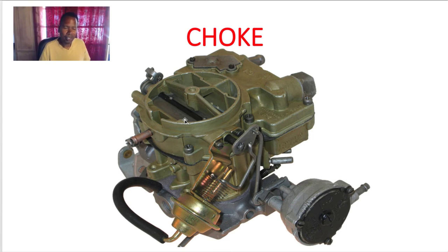I said this earlier, a cold start. Oh, I said this already. I forgot what I said. Oh yeah, when the car is cold, the air molecule is much denser. You need more fuel on a cold car. So what you need is a richer air fuel mixture. When this car is cold, this choke needs to be in its closed position when you first go to start the car up. As I said earlier, it works with the accelerator pump.